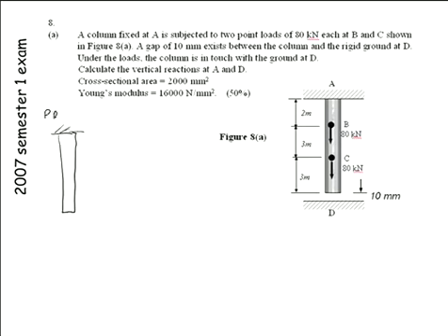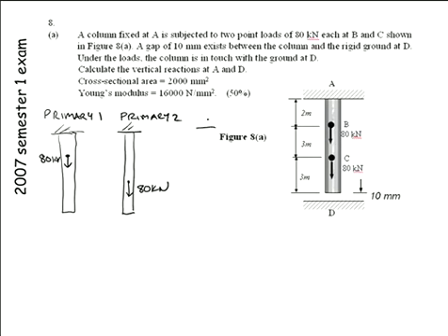So I would call this primary 1, where I apply one of my forces of 80. You could do them together if you want, but I think it makes things a lot clearer if you apply your two forces separately. And then we're going to assume we have contact. Well, we're not. We can work out how much it extends from the primary 1, primary 2 system. If that's greater than 10 millimetres, we know we have contact.